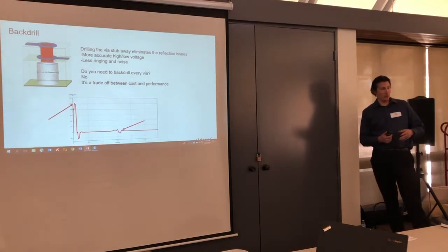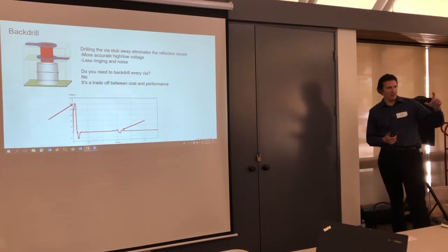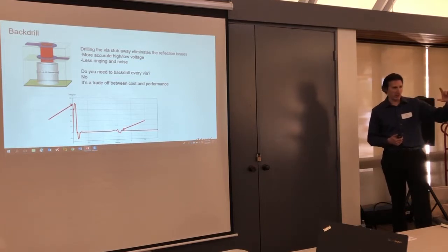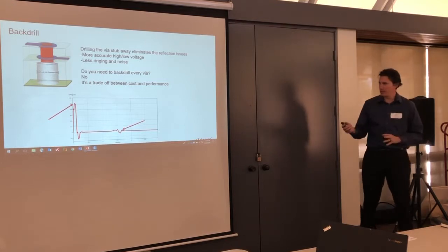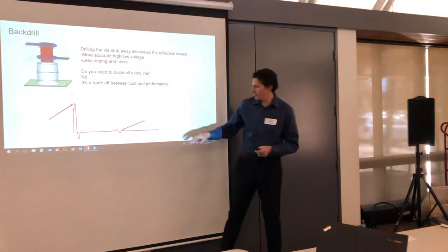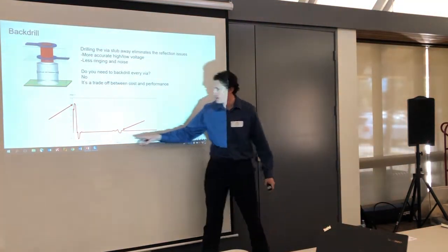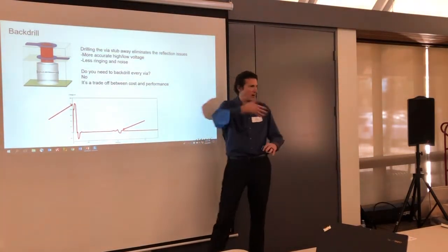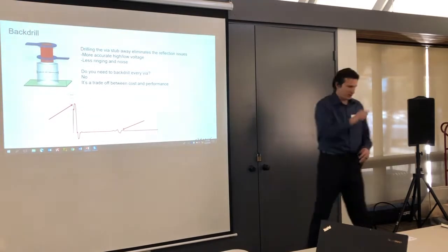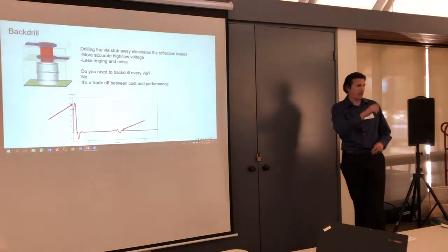Yeah, so that's when you almost have to start measuring the signal and seeing what the effect of a 6-layer via stub is going to be versus a 1-layer via stub. And the effect of that is probably going to be, if you imagine, at a very high abstract level, how long after the desired signal does that reflection noise come on top of your signal, right? The smaller stub is probably going to happen a lot faster than the larger stub.